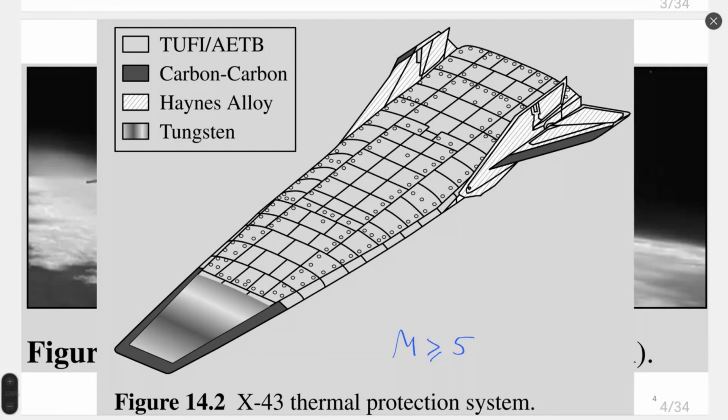By the way, this is not just typical for hypersonic applications, but also for some fast supersonic airplanes that fly at Mach close to 2.5, Mach 3. These airplanes are built intentionally with gaps in their fuel tank, for example, and during flight, due to thermal heating of the structure, these gaps inside the tank disappear and leakage of propellant stops. This is intentionally made to compensate thermal expansion and possible destruction of the structure.